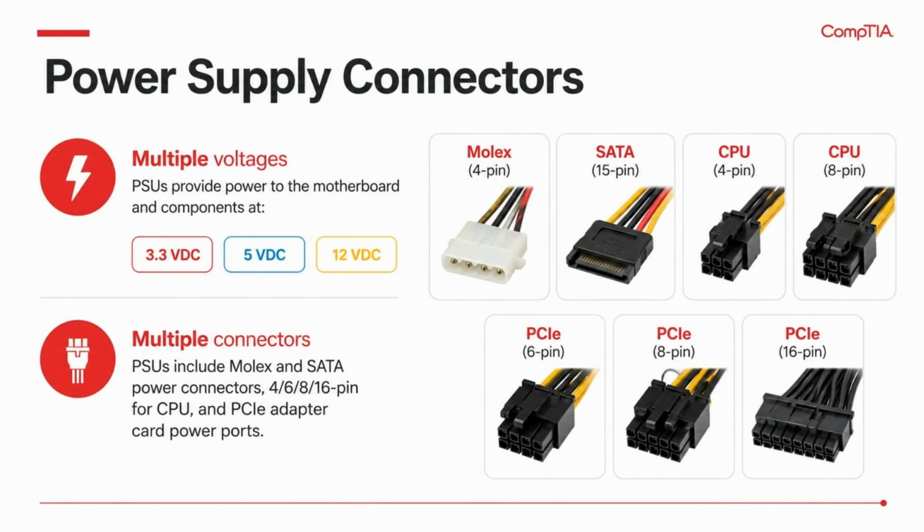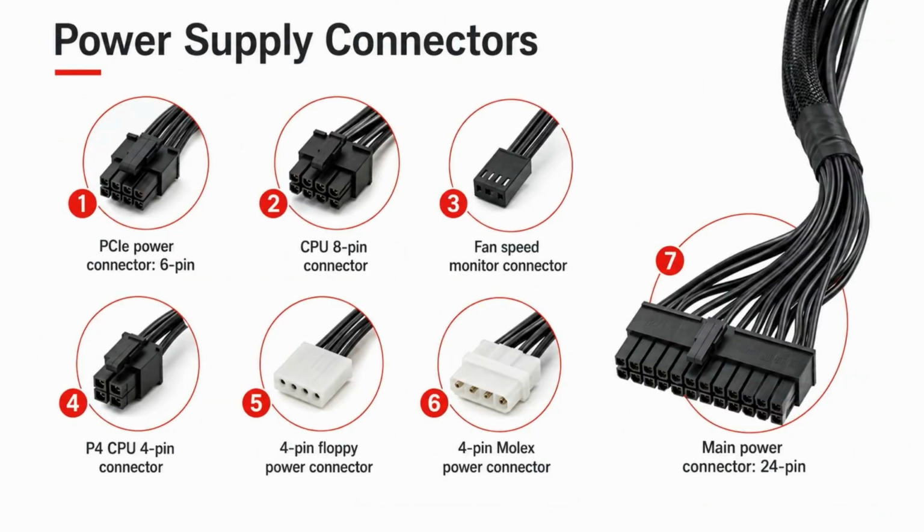PSUs provide power through various connectors to supply 3.3, 5, and 12 volts to your components. These include standard SATA and Molex connectors, as well as specific connectors for CPUs and PCIe graphics cards. Familiarize yourself with these common power supply connectors. From the main 24-pin motherboard cable to specialized 6 or 8-pin connectors for your graphics card, each has a specific role in powering your system.